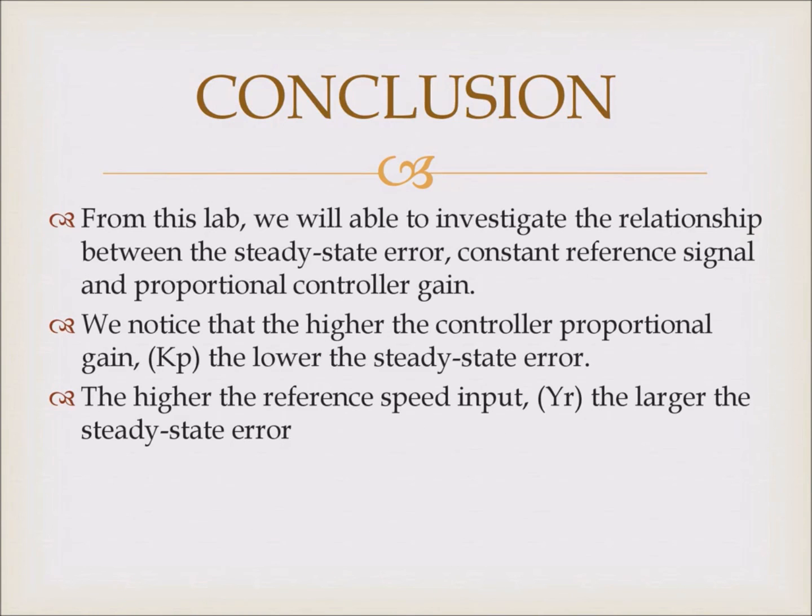From this lab, we were able to investigate the relationship between the steady-state error, constant reference signal, and proportional controller gain. We noted that the higher the proportional controller gain, the lower the steady-state error, and the higher the reference input, the larger the steady-state error.